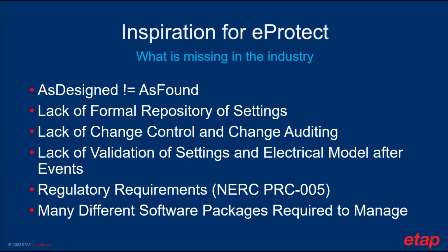And a big one at the bottom here is that many different software packages are required to manage. Each different vendor has their own software to connect to the relays. So now, rather than just one repository of settings, you can have 5, 10 different repositories of settings because you're using 5, 10 different software packages that have the history and all of the settings for your relay. So it can be cumbersome. You don't have everything in one centralized location.